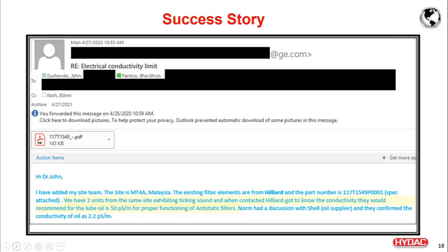and in this particular case, the oil utilized is Shell Turbo S4GX, which is a gas to liquid fluid, having very low conductivity, 2.2 picosiemens per meter. HYDAC has experience with that and has resolved issues with that. And now we are being asked to help GE to resolve that issue as well. So I would like to thank Airline again for their continuous engagement, promoting this StatX technology as well as the stat-free technology and helping to educate the OEMs as well. So thank you for your support.